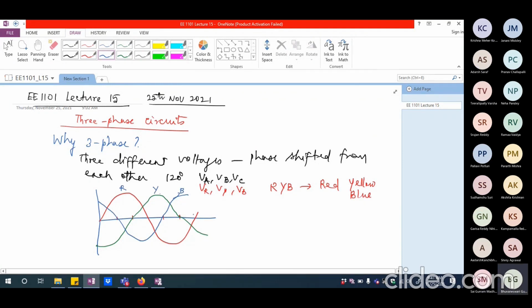These are the three voltages that are going to be generated independently. But when we have three phase voltages generated independently, very clearly, there will be three phase currents as well. So if I'm going to have a resistive load, for example, I will have probably the current exactly in phase with the voltage. So I'm going to have something like this for R phase current.